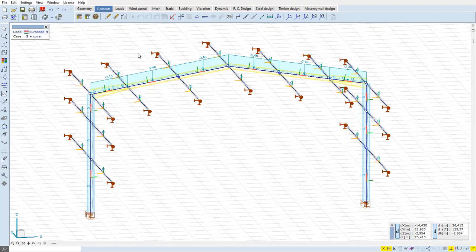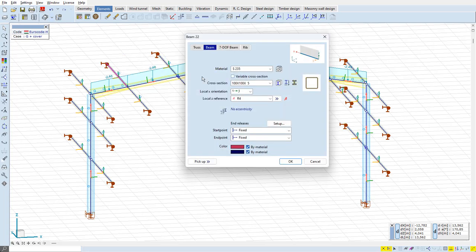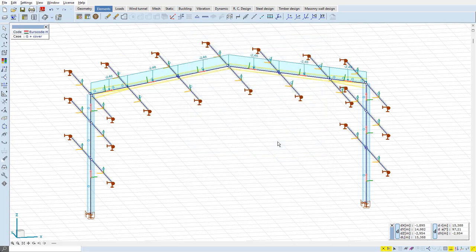In the following model, a simple hinged portal frame is presented. The rafters are divided into two segments, one with hinge and one straight. The straight part is going to be investigated. It is getting supported in three different ways. At its beginning, it is a rigid connection. After it comes a semi-rigid one.